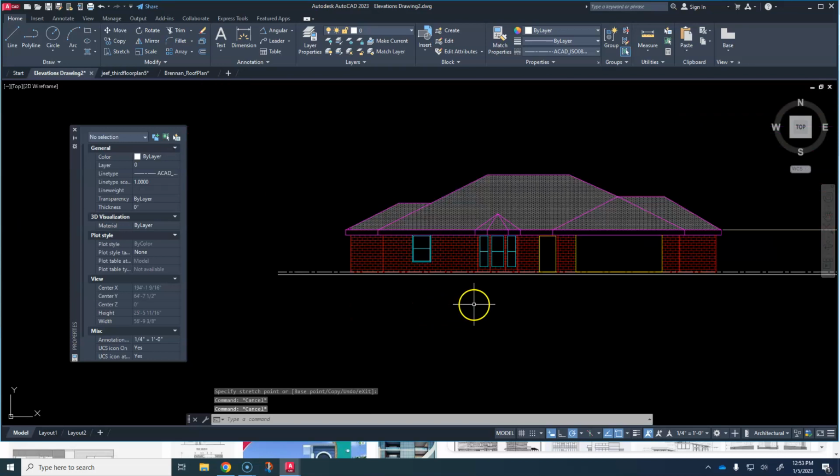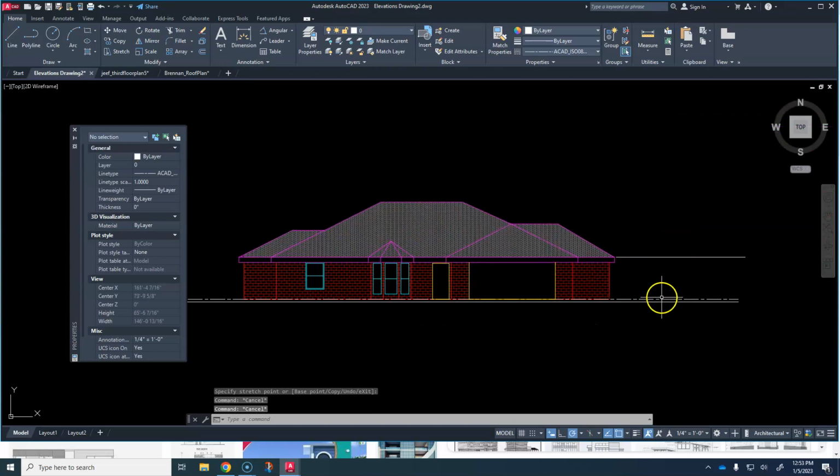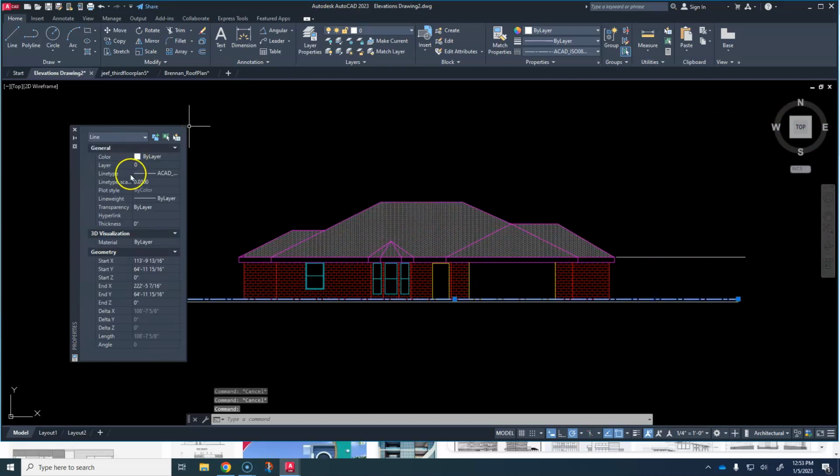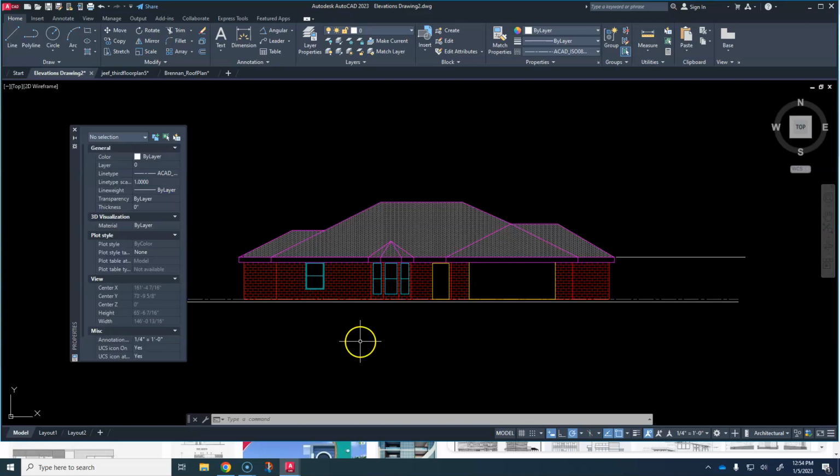All right, we are going to change the value of that also with our line transparency by layer. Right here, let's just put in 50 for now, see what 50 does for transparency. And of course we have to hit the escape button to get off of it.